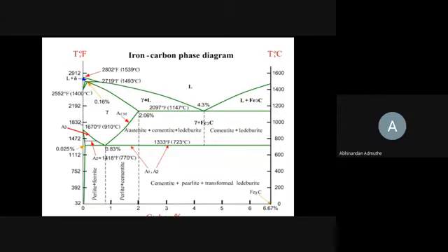But in Greek letters, alpha, beta, gamma, delta comes. Where is the beta iron then? You can see it here, alpha, gamma, delta. There is no beta iron. But if you see the literature, initially it was thought that iron from 768 degrees centigrade converts into non-magnetic. So initially people thought that it is due to phase transformation, iron has lost magnetic properties. So that's why the iron present from 768 to 910 degrees centigrade they referred to as beta iron. But later on they discovered that iron has lost the magnetic properties not due to phase transformation, it is due to electron spin motion.